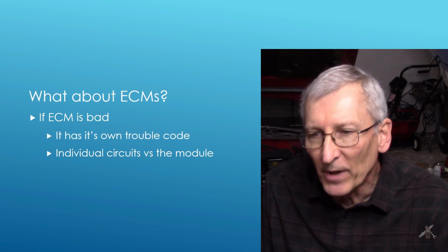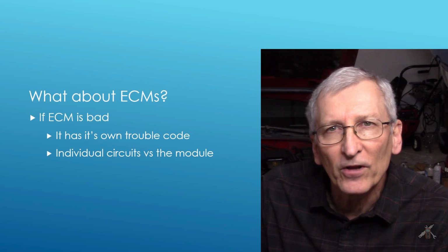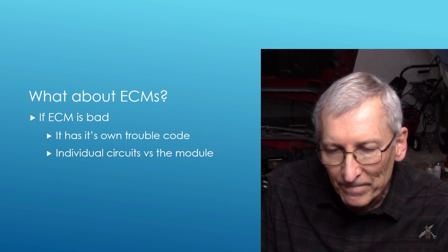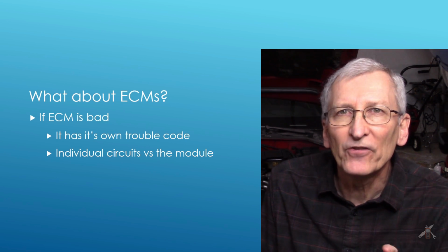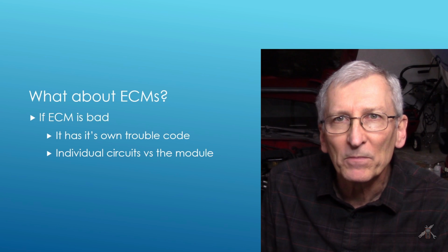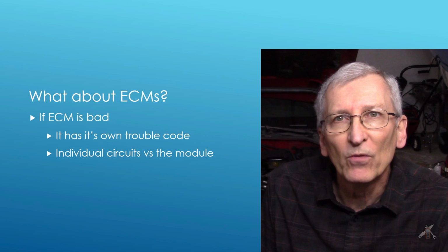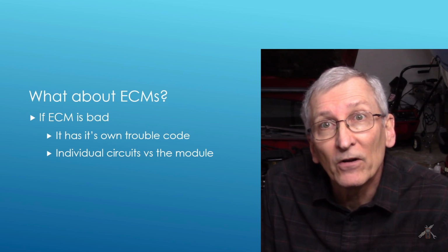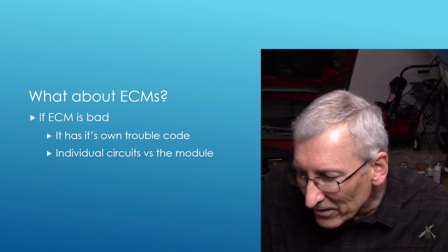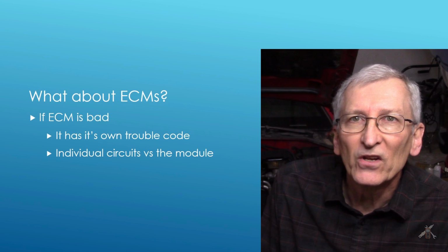I also got questions about ECMs. What about if your ECM is bad? My engine's running bad, should I just put in a new ECM? Generally speaking, the advice is no, don't do that. I've done it before. When I was at the end of my rope and couldn't figure out what was wrong, I put in a new ECM in my daughter's car, in her Buick, years ago. Bought a rebuilt. Didn't make any difference.